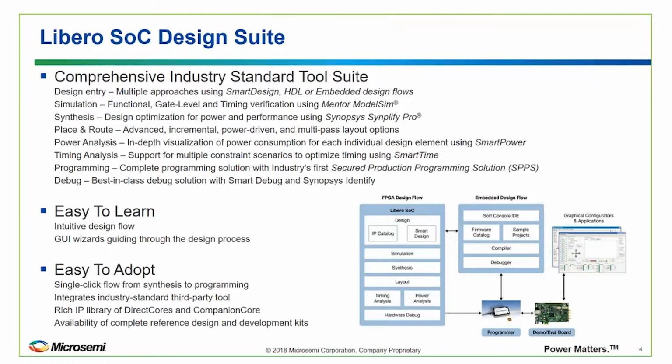You can use your traditional HDL, either VHDL, Verilog, or System Verilog. And we also have embedded design flows for designs that feature processors, either hard processors like we have in SmartFusion 2, or a soft processor like RISC-V or Cortex-M1. Libero includes the ModelSim simulator from Mentor Graphics for functional simulation, gate level simulation, and timing verification after running